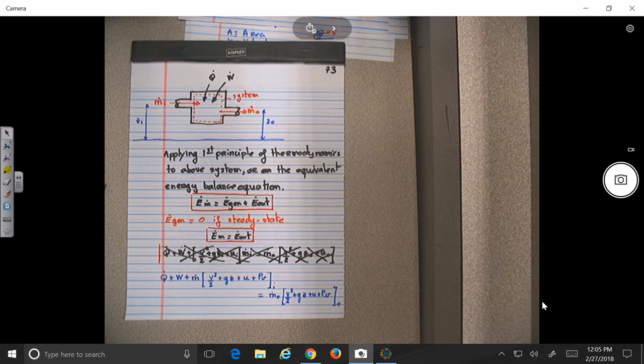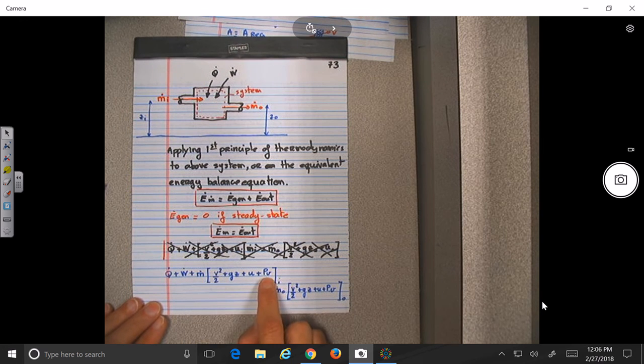So the role of the compressor is to slow down the flow as much as you can so you can increase the pressure. It's the same thing, you know, if somebody tries to get out of the door and you have the biggest guy on the door and just stop the door and everybody starts pushing, you're just going to keep increasing the pressure, no? But if you start going out, then the pressure is going to go down. So the ideal case is to be able to build all that pressure there so that once you move into the volume, you can produce as much work as possible with the P dV, no? Let's say the pressure is constant, the volume is constant, you do PV. So basically, that's the explanation for this term over here.